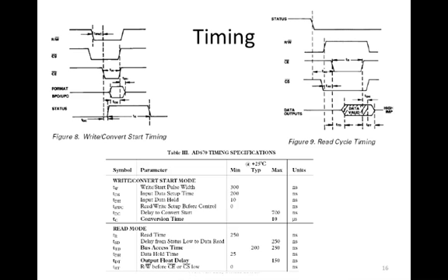When you see something wrong, think about it. Look at these datasheets, look at the delay, look at the timing. Try to play around with the timing of these two parts or several different parts to see if there is any possibility of an inconsistent design.